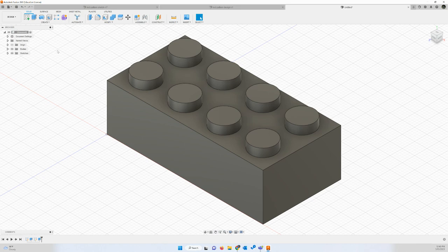So let's do this. Let's go fillet. Now, do I want to go select every one of these edges to fillet? Notice over here in my window, it says on my selection, I can select edges, faces, or features. Features, where am I going to find the feature? The feature will be down in the timeline where I select that extrude that I just did to extrude the 8 pins. But let's go ahead and select the edge on the first pin.